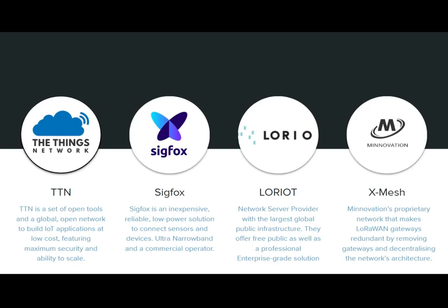Sigfox employs a token and firewall approach. Power consumption is also very similar. TTN is slightly lower with a peak performance of 44 milliamp versus 49 milliamp for Sigfox. And sleep of both protocols is about 1 microamp. So very, very similar in terms of their power consumption.